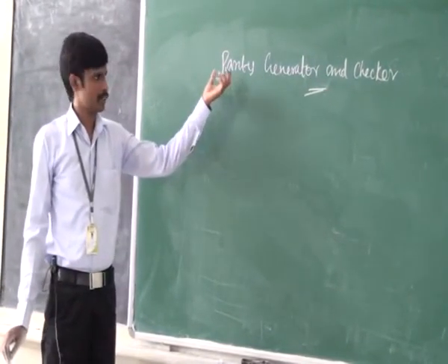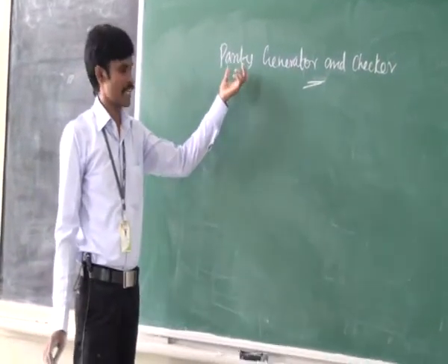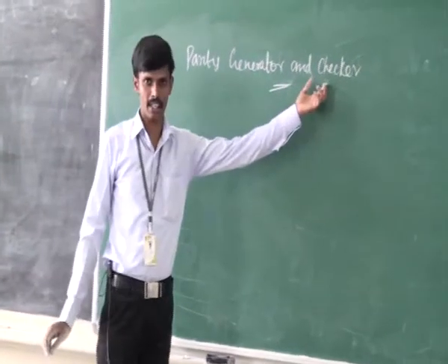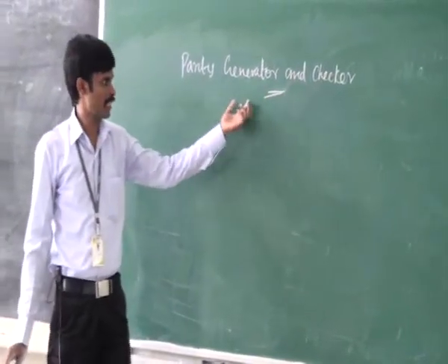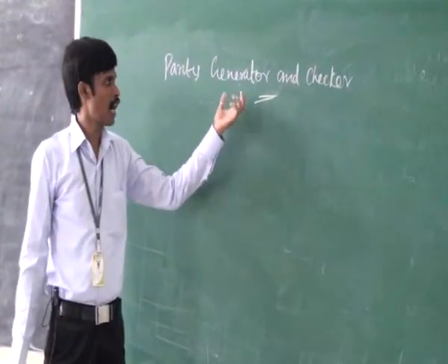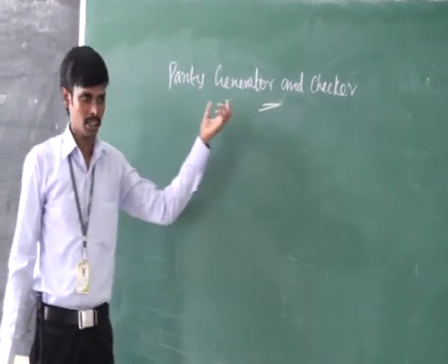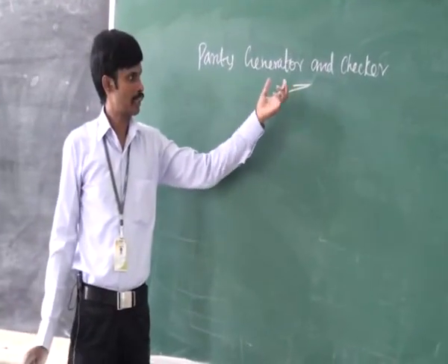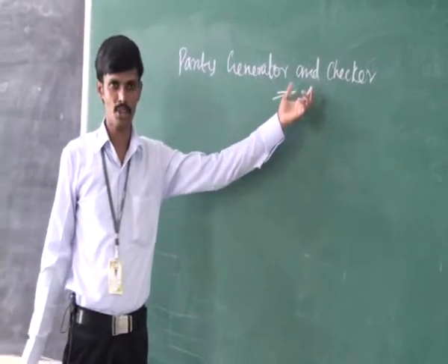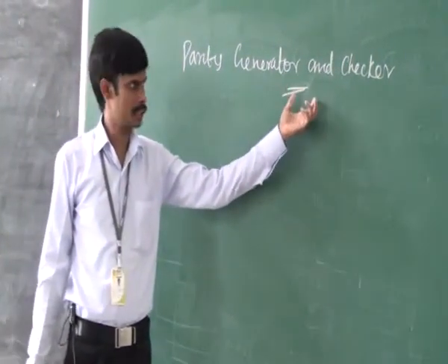The parity bit included with the binary message is transmitted and then checked at the receiving end for the errors. Then the parity checker will detect the parity of the received message and compare it with the parity of the transmitted message. If they are the same, then it understands that there is no error. Otherwise, it understands that the error is present.